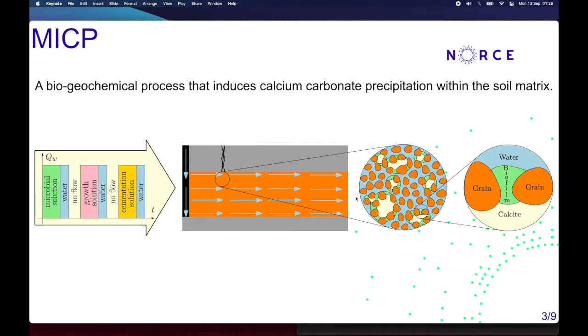We consider the limiting factor in the growth solution to be the oxygen. This assumption can be justified since oxygen has a limited solubility in water, while the other components can be injected at higher concentrations. Assuming enough calcium concentration in the water, we model the calcite formation as a function only dependent on the urea and the biofilm. This assumption can be justified since calcium can be injected together with urea in the cementation solution and will thus distribute in a similar manner, ensuring that both concentrations are high in the location where calcite precipitation is aimed.